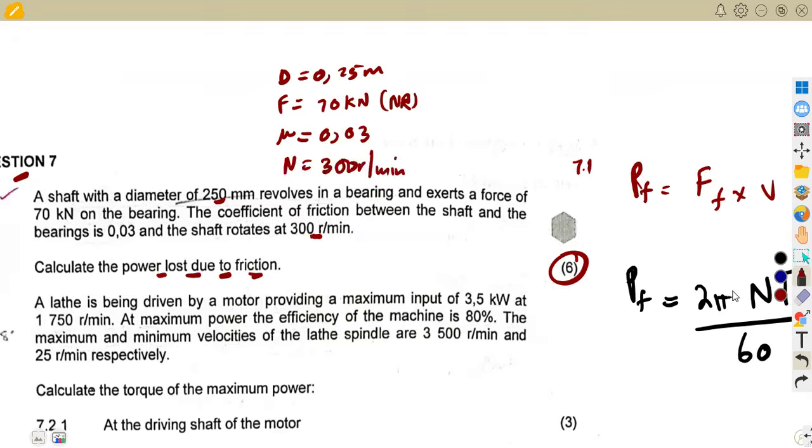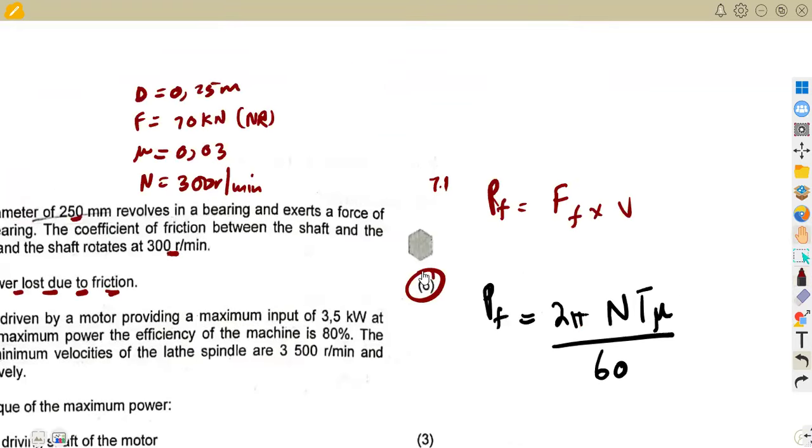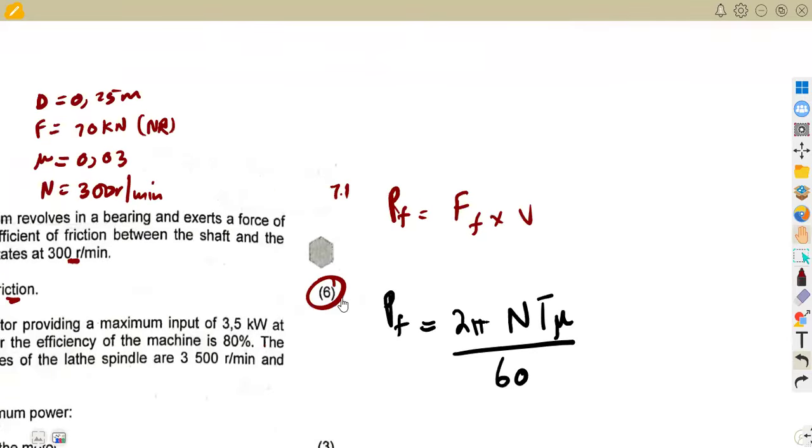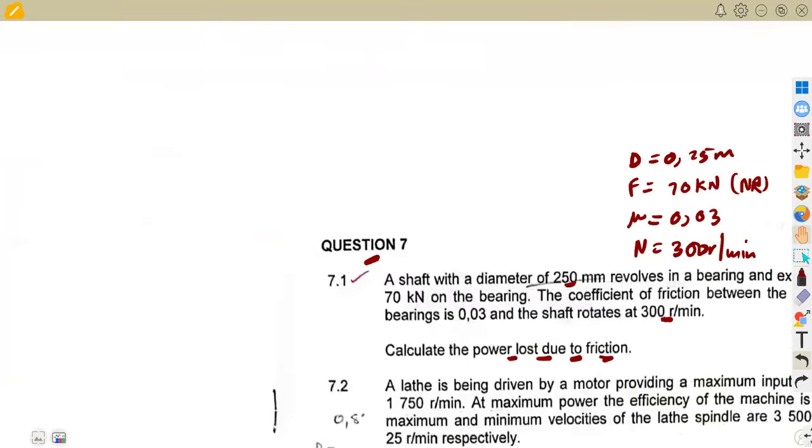Let us calculate the necessary information. The formula that involves the torque is the longer one, with a lot of things to consider, so I'm going to start with it. From this formula, the frictional power is 2 pi n times the frictional torque over 60, where n must be in revolutions per minute. So we need the frictional torque. Remember, torque is the product of force and radius.